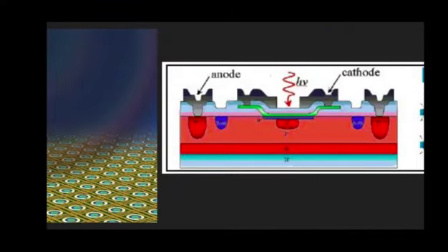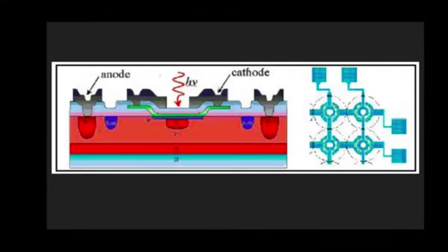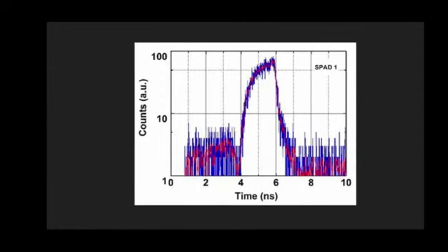This then collides with other atoms in the depletion region, allowing for even more free electrons, as the kinetic energy of each electron after the collision is sufficient to knock off an electron from the atom. The ratio for this positive feedback is one colliding electron to two free electrons in the conduction band after the collision. This continuously occurs until an avalanche of free electrons reach the cathode and a very rapid and strong current is onset, which can reach up to a couple of milliamps.